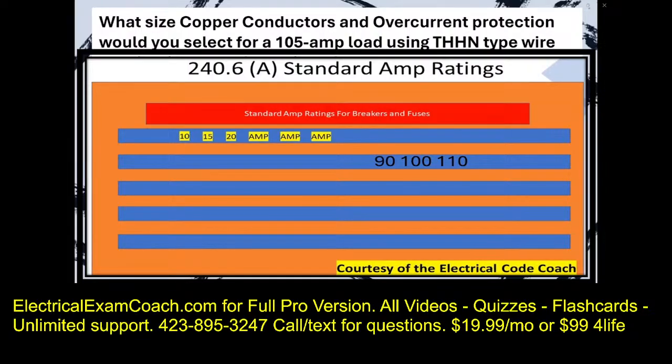I've seen them. I've worked with them out in the field, but they're not very common. Usually out in the field, we'll jump from a 100 to a 125 for like sub-panel sizing. But you have to be careful here. Always go to the table because the correct answer for this question is actually a 110 amp breaker.